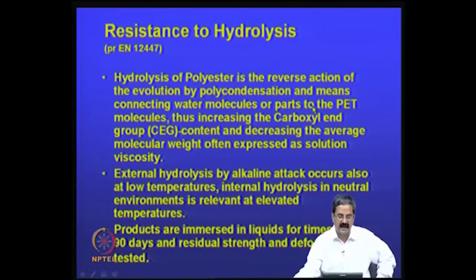This hydrolysis is again something that, hydrolysis of a polyester is a reverse action of the evolution of polycondensation and means connecting the water molecules or parts of the PET molecules, thus increasing the carboxyl end content and decreasing the average molecular weight, often expressed as solution viscosity. Actually, this hydrolysis is another serious problem in many of the polyesters. So we have to take care of this, and you need to create proper conditions.